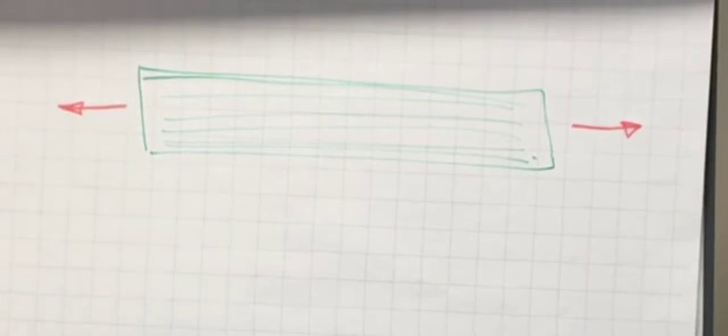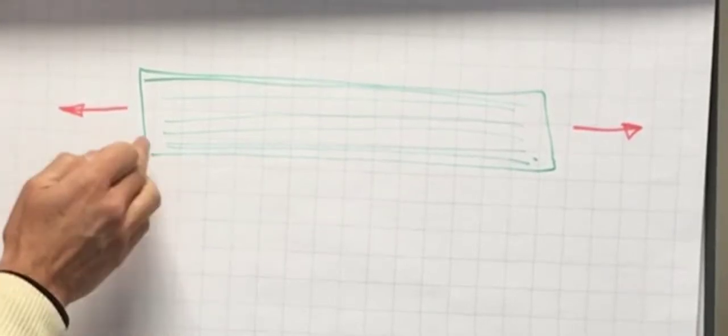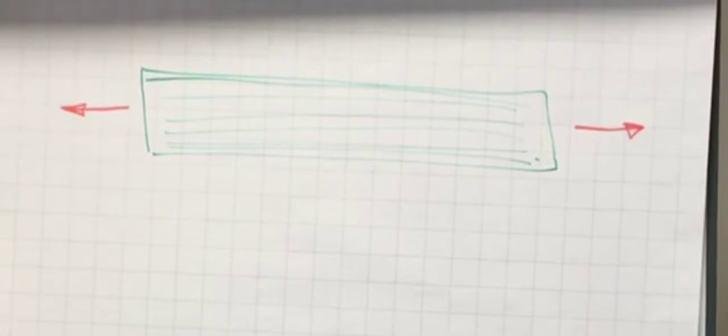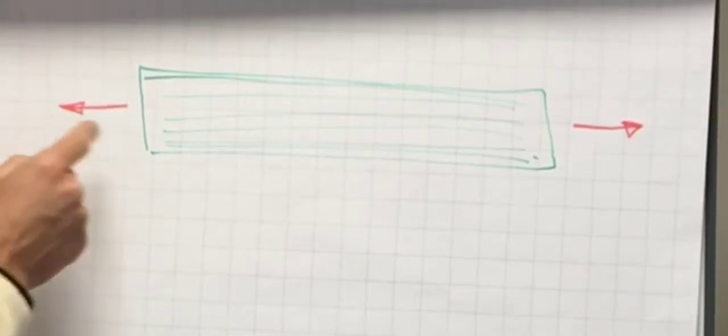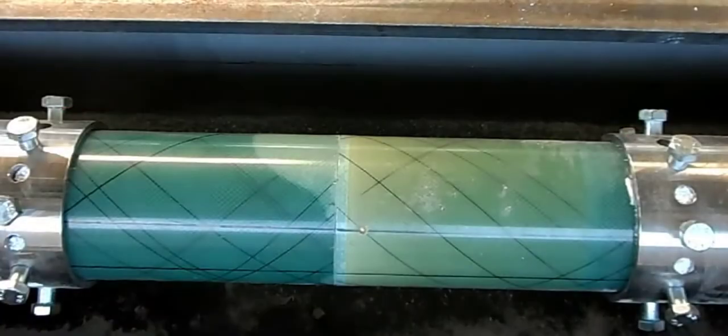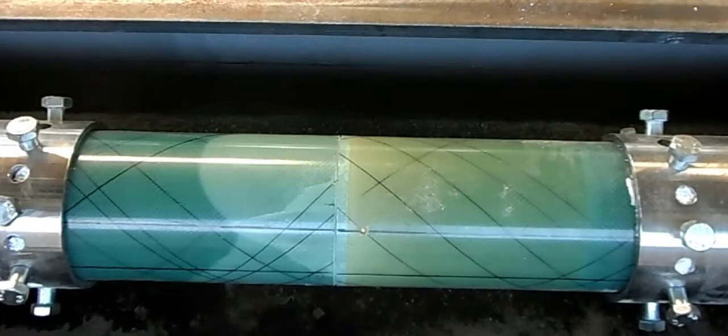And in this situation we don't have a big problem because the resin that is in between the fiber hardly takes any load. All the load will be distributed through the fiber from one end to the other end of the piece of material. So when we do a test like this and we have a load in the direction of the fiber, we will not see microcracks. The failure mode will most likely be rupture, fiber failure.